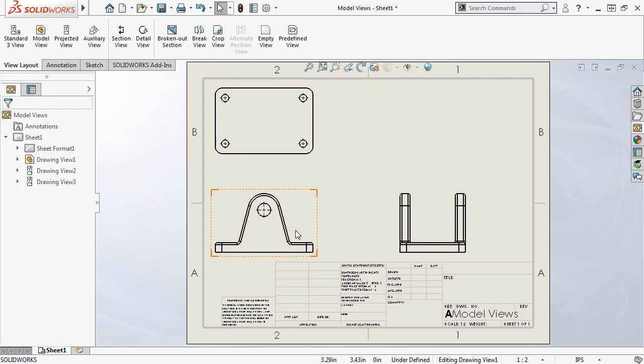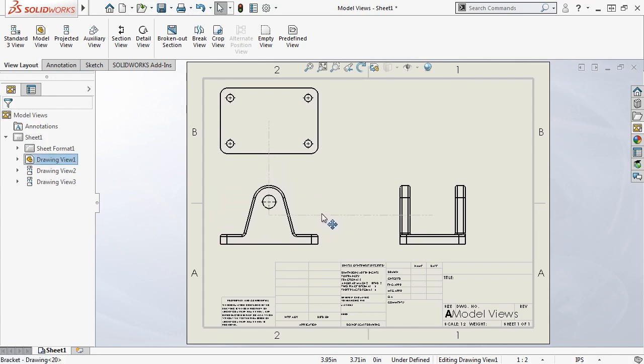Projected View menu. One aspect that is really nice and convenient about creating projected views, as opposed to simply dragging and dropping additional views from the View palette, is that the created views are automatically aligned. So, if you move the base view, the projected views move with it and maintain the alignment.